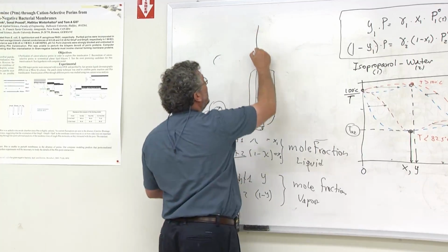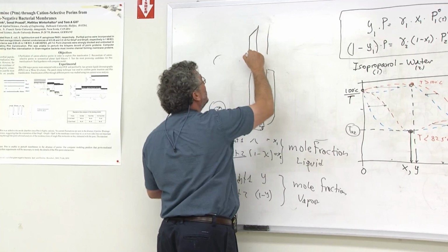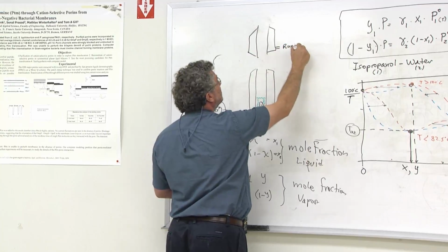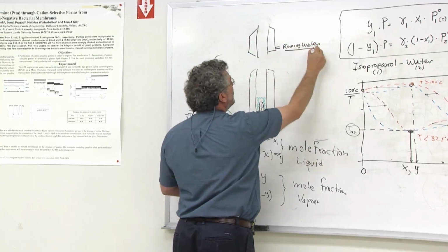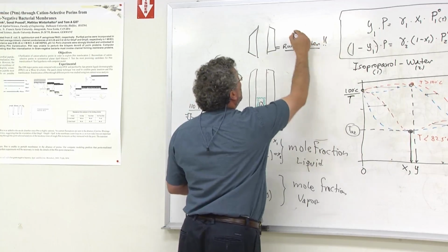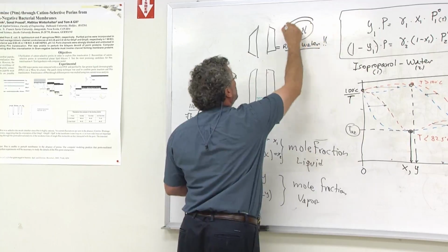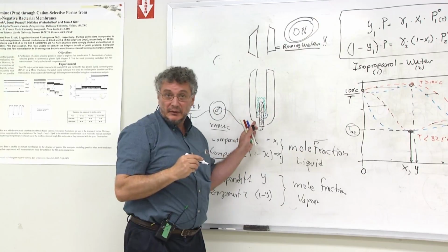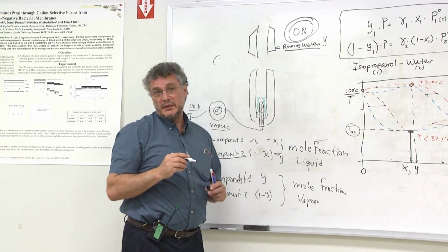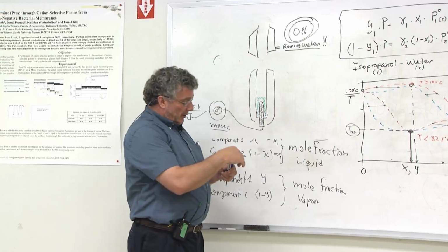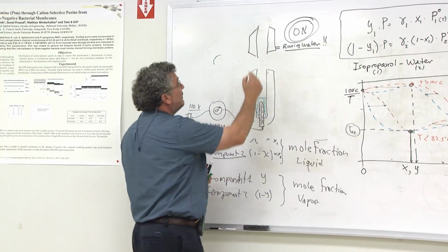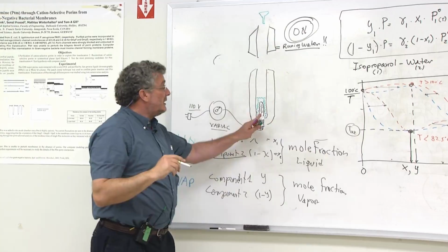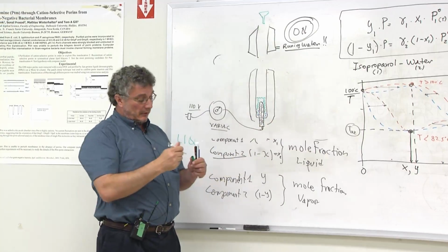On the top there will be a condenser, as we explained before. That condenser will have some running water. And this running water must be on at all times. Before you even plug the heater, you have to make sure the cooling water is running. Because you are going to feed this liquid from the top here, another thing that's important is that this has been cooled down if you're going to replace it.